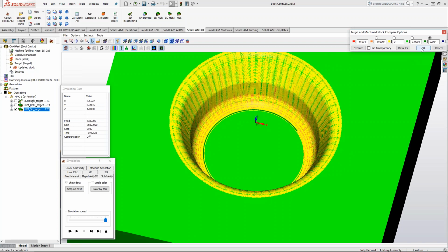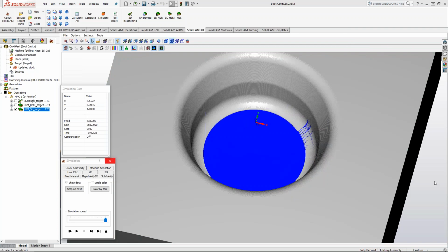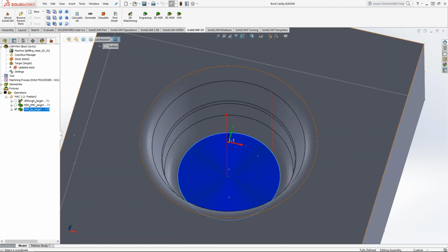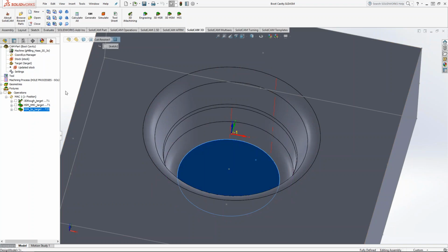So it can still go up in the tool changer, and it's just for that tool only, and you mount this little fan blade on there. And you're showing me a comparison, with it and without it, and surprisingly enough, this little tiny fan blade was actually able to throw out all the chips and keep all the chips out of there with the aluminum that he was cutting, so he wasn't getting any recuts.